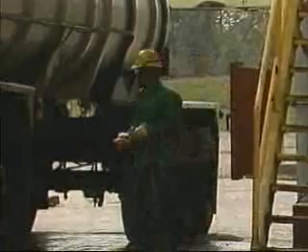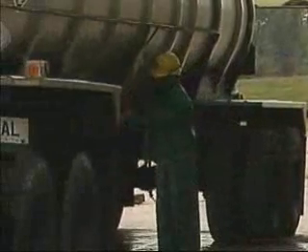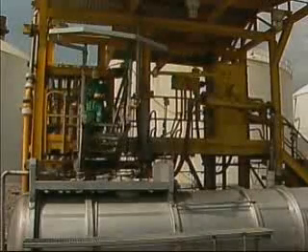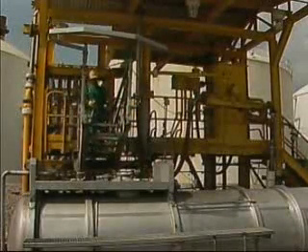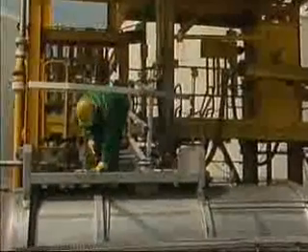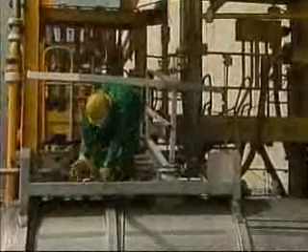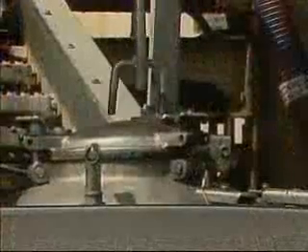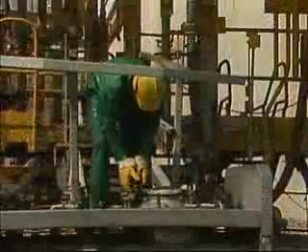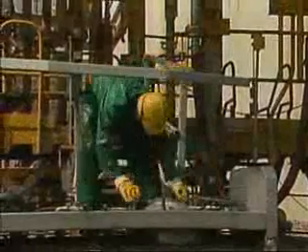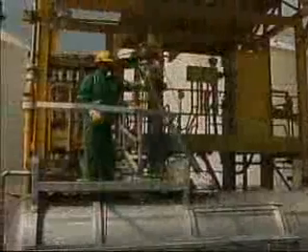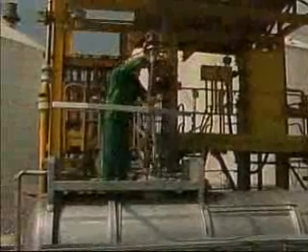After he completes the inspection, the operator attaches a grounding cable in order to ground the tank truck. Then he uses the access equipment to reach the tank and prepare for the transfer. Before he opens the manway cover, the operator relieves any excess pressure in the tank by slowly opening the bleeder valve. Once pressure has been relieved, the cover can be unbolted. The operator then opens the cover and looks inside the tank to make sure that it's clean and ready to receive product. Next, he lowers the loading line into the tank.